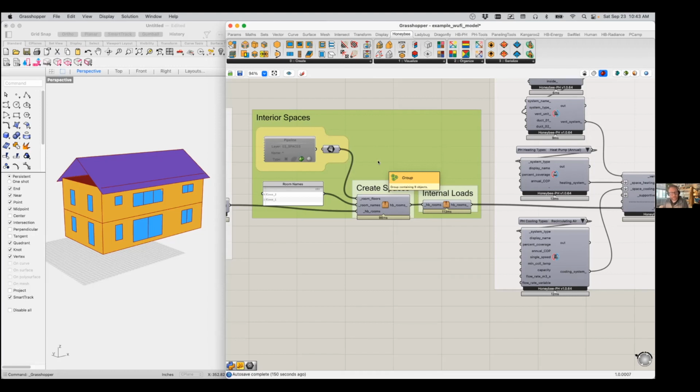So you might say, oh, the kitchen has 50 CFM of airflow. The bathroom has 25 CFM of airflow. And then other program-related items like lighting, electric appliance, energy consumption, occupancy, and other use-related specifications. So those kind of internal uses get assigned at the space level.